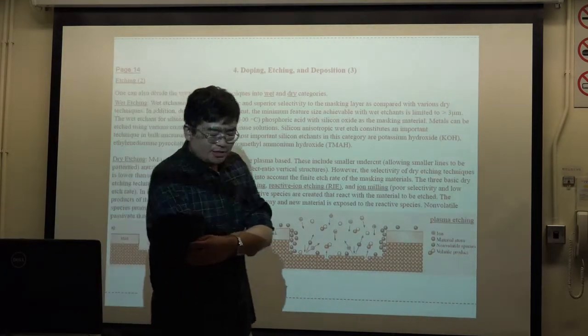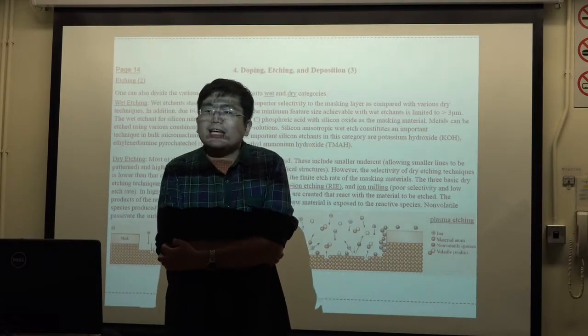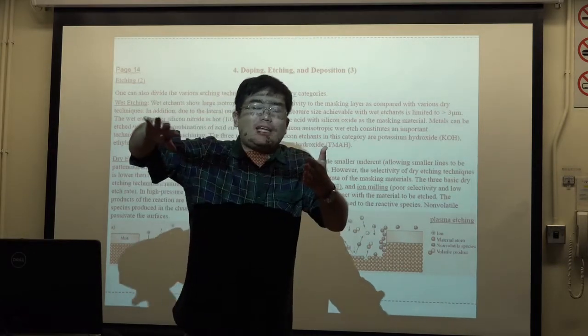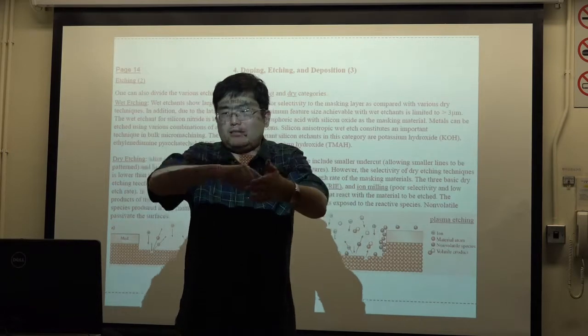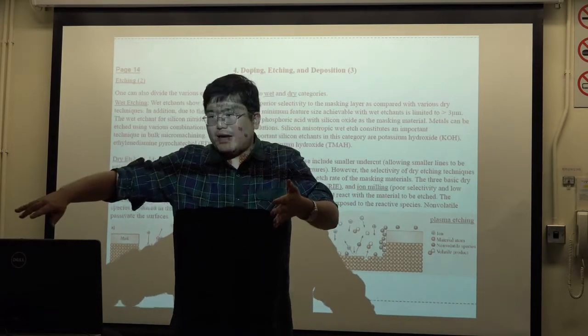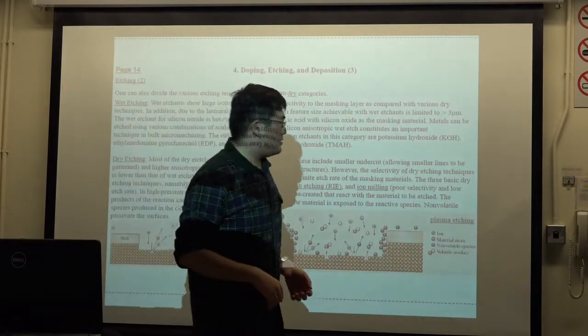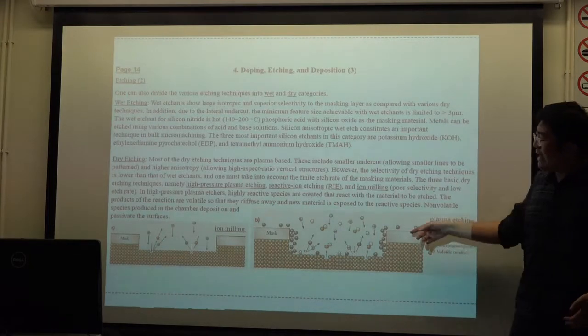Passivation is very important if you want to remove dangling bonds. Silicon has some dangling bonds, so it has very strong surface recombination. I mean, electrons and holes may recombine here, so they use surface passivation to passivate the surface. So in plasma etching, interestingly, they